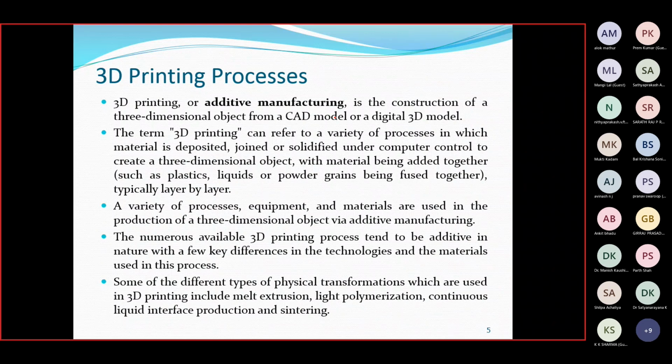You can't always heat and generate a particular temperature to melt down the material and combine it together. Sometimes you have to paste. So we have pasting methods also. One layer is pasted upon another and then pressed hard. That was basically used in the making of plywoods. You have seen those boards and plywoods. What will the machine do? It will give you one thin paper, and on that thin paper they will paste another thin paper, and then they will apply huge pressure on that at a particular temperature. Then all the paper will be joined together. In Sunmica we used to generate this type of thing, by this process.